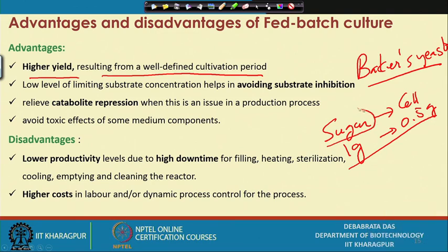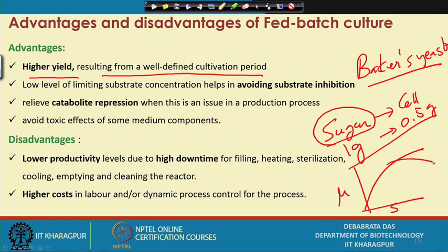We shall have to use the amount of sugar input to the system. Now, we have seen before that as your substrate increases in a batch process, and if you increase the substrate further, then we find some kind of substrate inhibition. If we plot mu, we have this no inhibition curve, and then some kind of substrate inhibition that takes place. Now the question comes: as soon as you go for the highest substrate utilization, the activity of the organism will be reduced to a great extent.